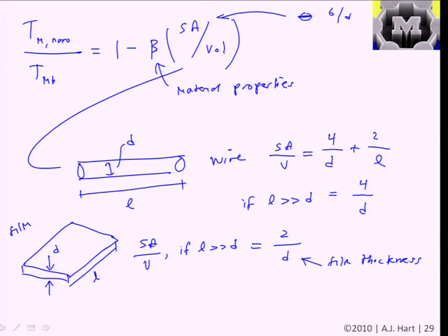So just to lay it out formally, if we said T, the bulk melting point minus the nanoscale melting point divided by the bulk melting point, goes as 3 to 2 to 1 for a sphere versus a wire versus a film.